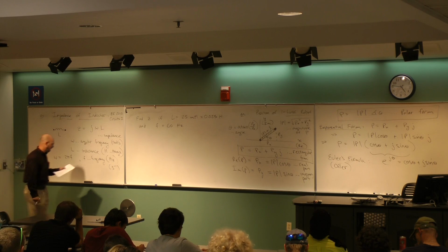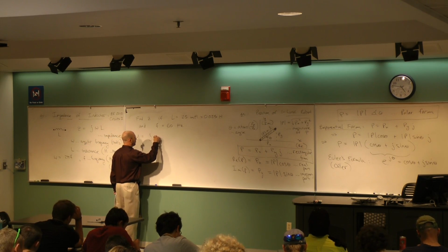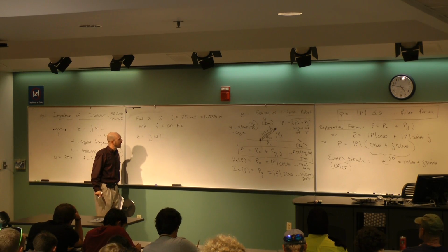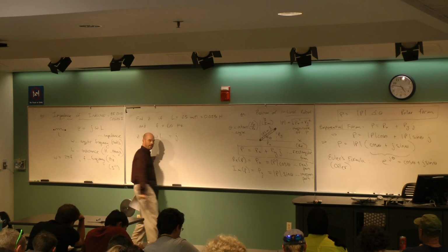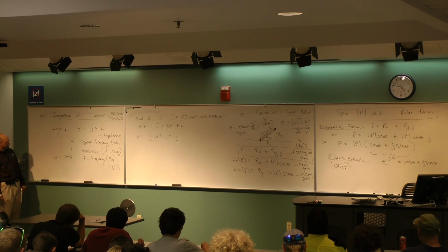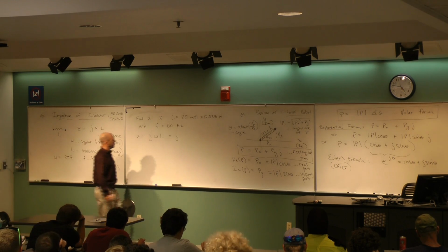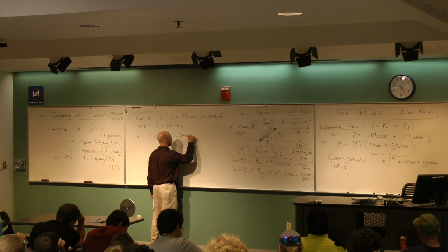All right, so let's write this down. Z is equal to J times omega times L. J omega L. So it just means literally put the numbers in here. If f is 60 hertz, then omega would be what? It's going to be 2 pi times the 60 here.